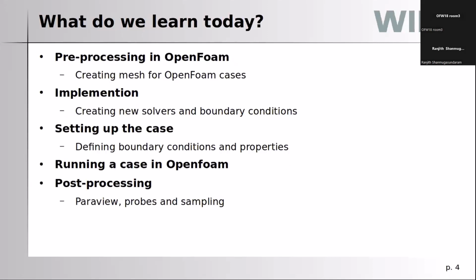So what we will be learning today is, initially, to post-process in OpenFOAM and create meshes for the seabed liquefaction. Then I'll show you how to implement the governing equations inside OpenFOAM. After that, I'll show you the case setup for the test case study for the liquefaction, and how to run the case using this numerical toolbox. Finally, I'll show some ParaView steps for viewing the results, and some function options like probes and sampling.